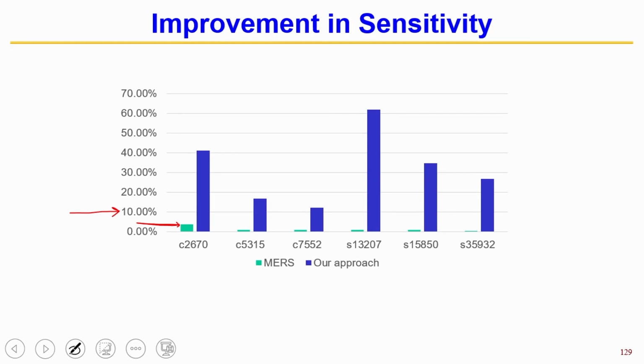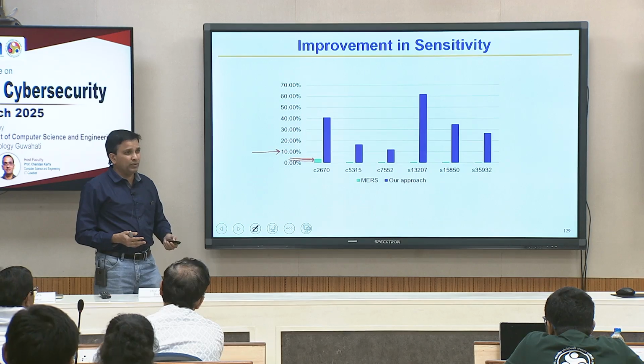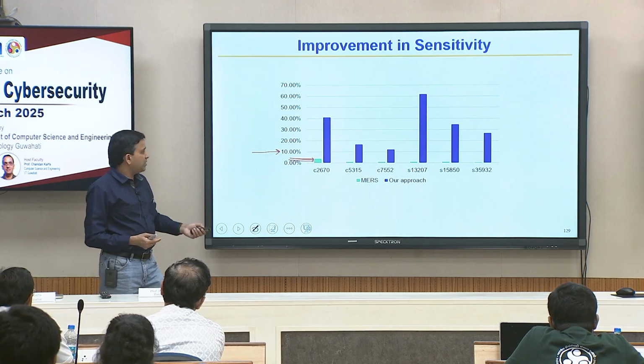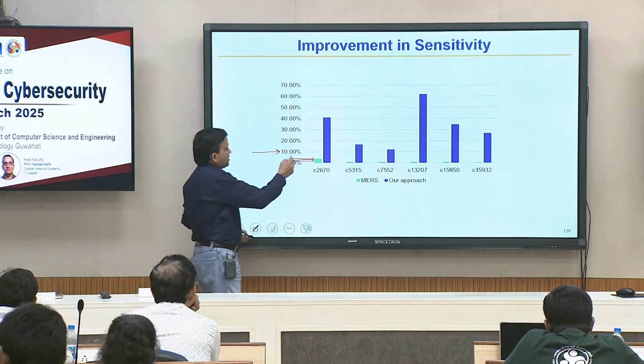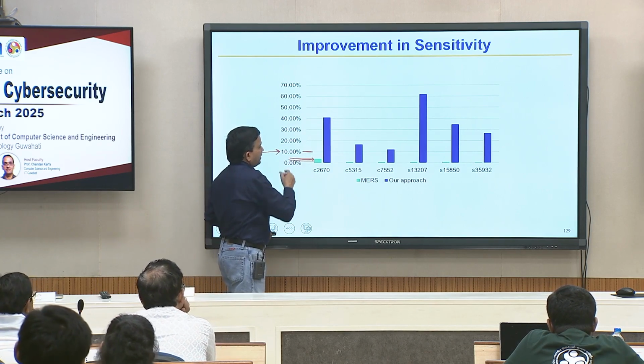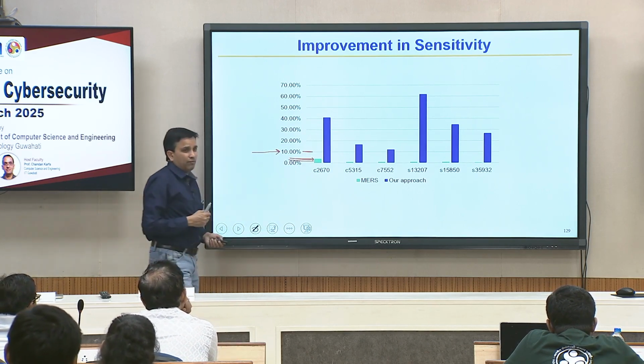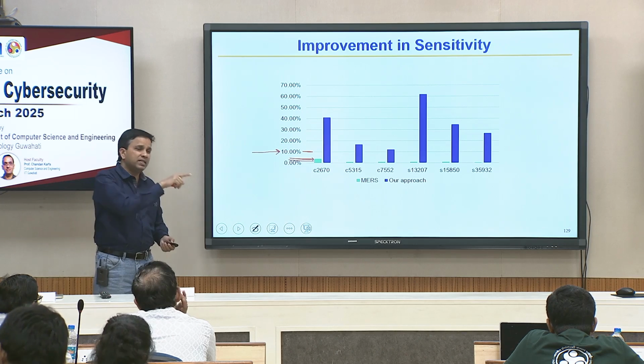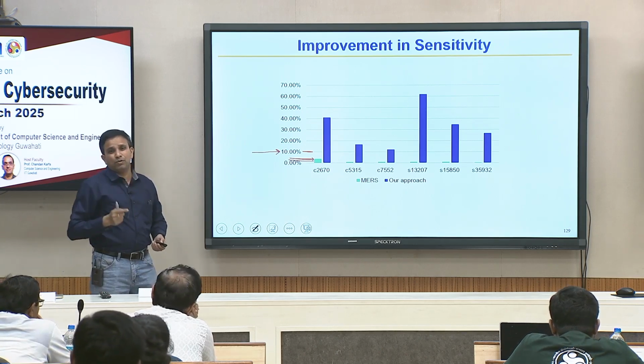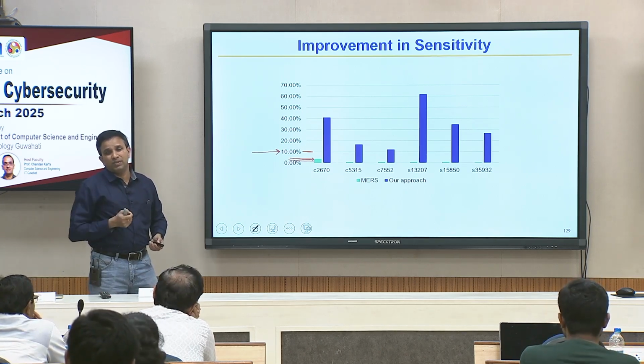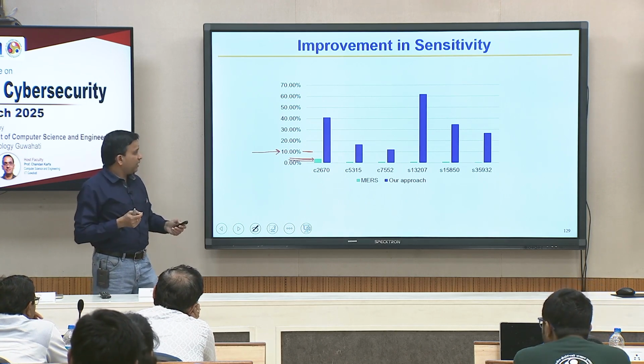If close to 1% sensitivity or less is measurable, then existing work will still be able to detect the Trojan. But if today's oscilloscopes are not able to do that, then you can safely say that unless your Trojan sensitivity is higher than 10, existing approaches will fail. So it has to be realistic, based on what oscilloscopes on the market can measure.